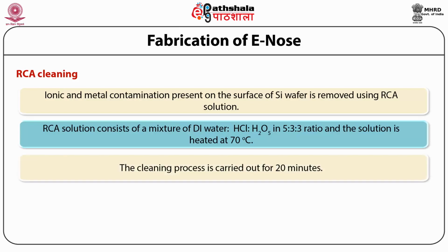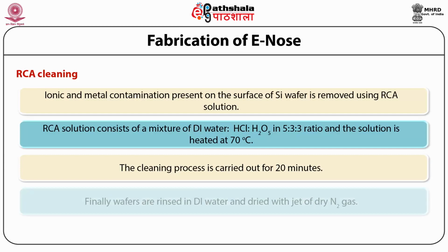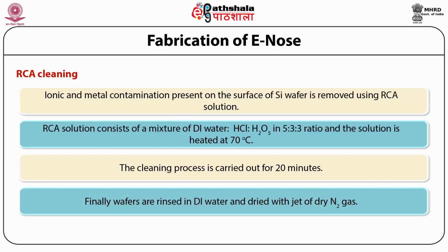Here the cleaning process is carried out for 20 minutes. Finally, the wafers are rinsed in DI water and dried with a jet of dry nitrogen gas.